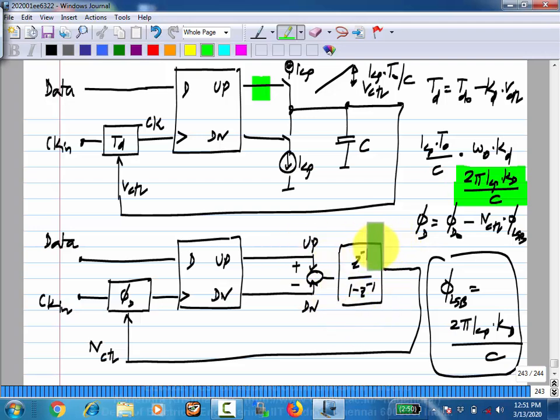It's a lot easier in binary computation to make it wrap around after 2 to the n steps. That's why you don't divide it into 100, you divide it into either 64 or 128 and so on. But you get the idea, right? This business of digital clock recovery is essentially phase selection based on this digital phase detection.